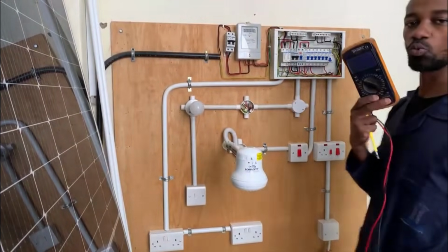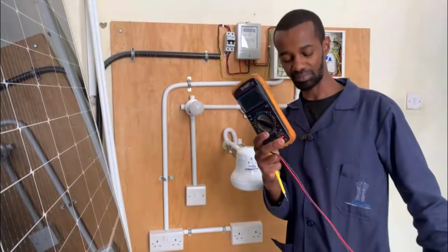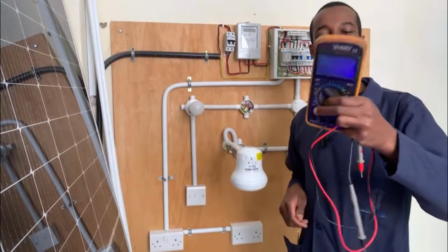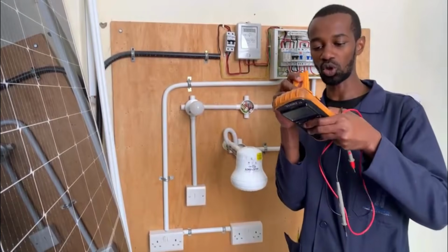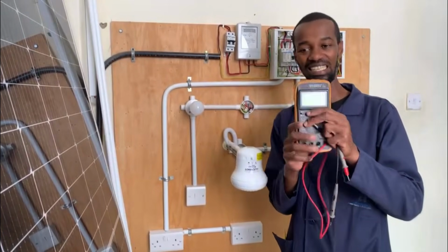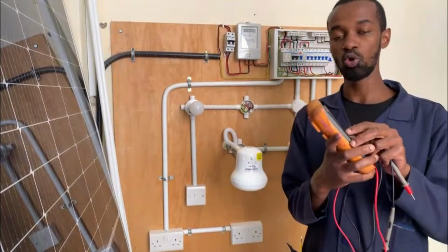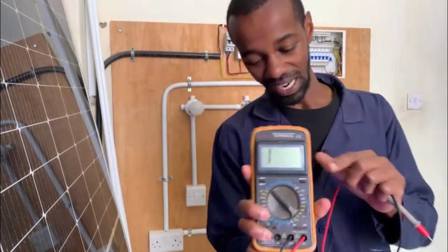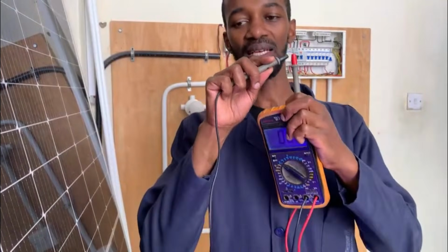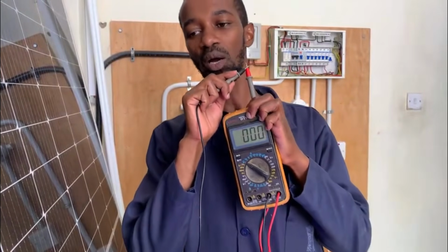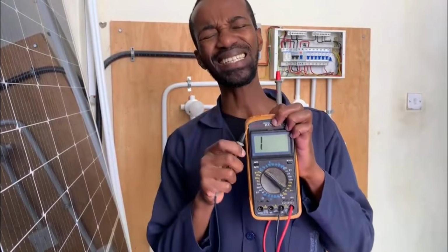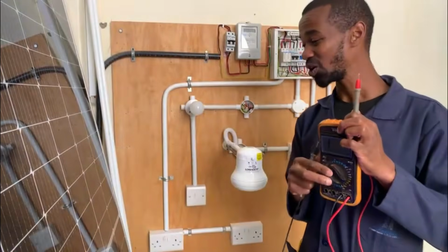Now, here is where this important instrument comes in, the multimeter. Digital multimeter. On our yesterday's live stream, we talked much more regarding a digital multimeter. In fact, yesterday we covered much to do with continuity test. We agreed that continuity test is whereby you bring these probes together and you hear that beeping sound, and it will shift from a 1 to 0. What does that mean? From infinity to continuity.